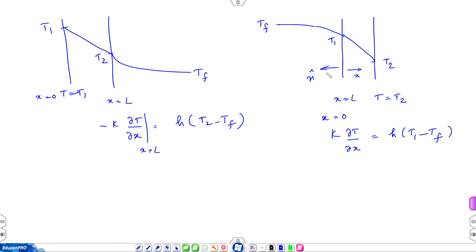So, these boundary conditions will keep changing from one problem to another, but the form of the solution within is either linear for Cartesian coordinates and logarithmic for cylindrical coordinates. And the log term vanishes if it were to be a solid cylinder, because you can't deal with r equal to 0, where the log term is not defined.